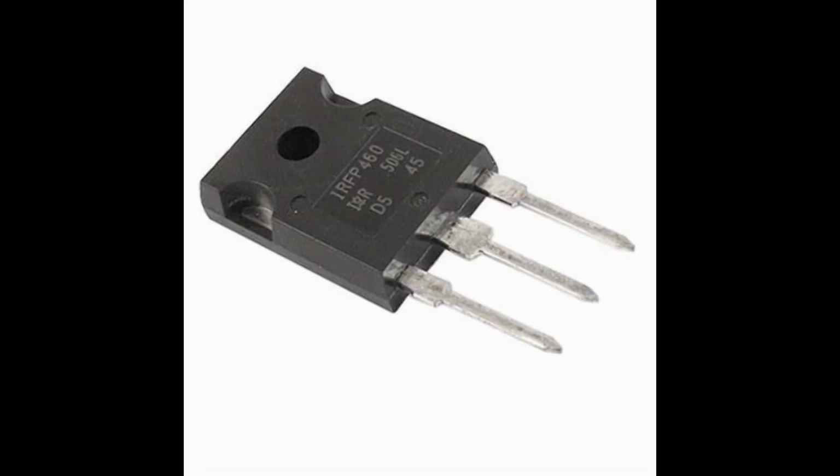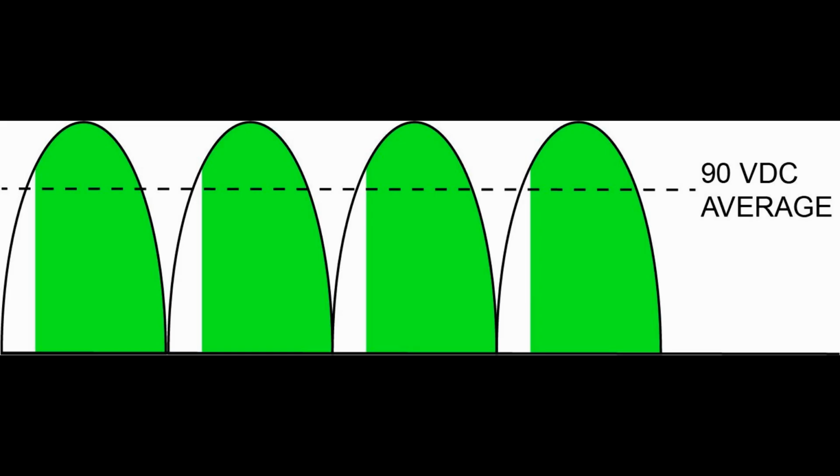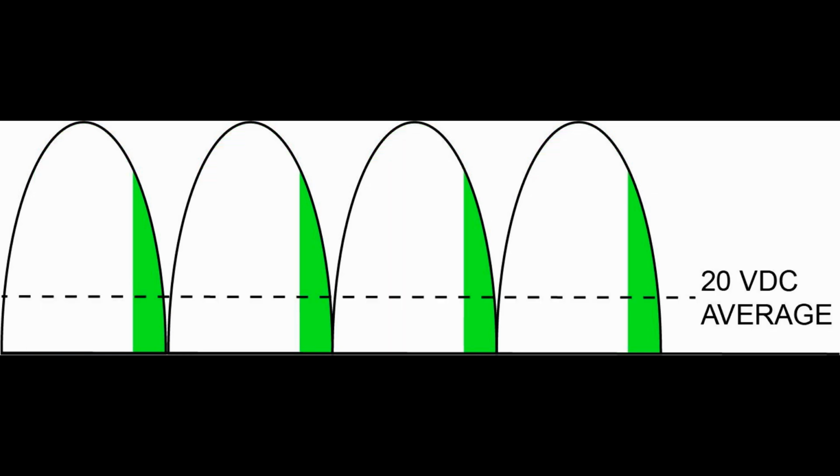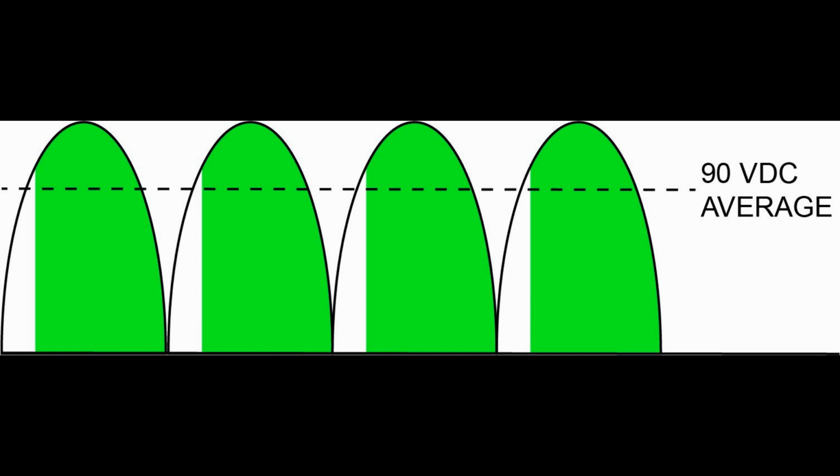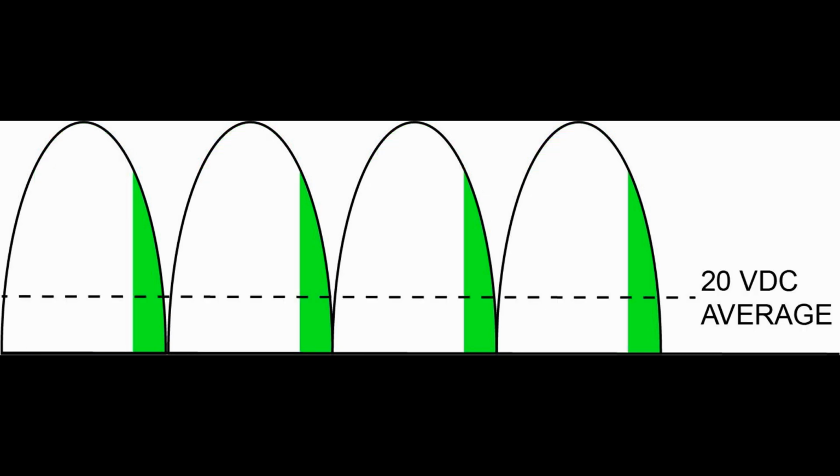But special types of switching devices must be used, such as power transistors and devices of the thyristor family. Then you can remove any part of that current wave and control output voltage as you like.